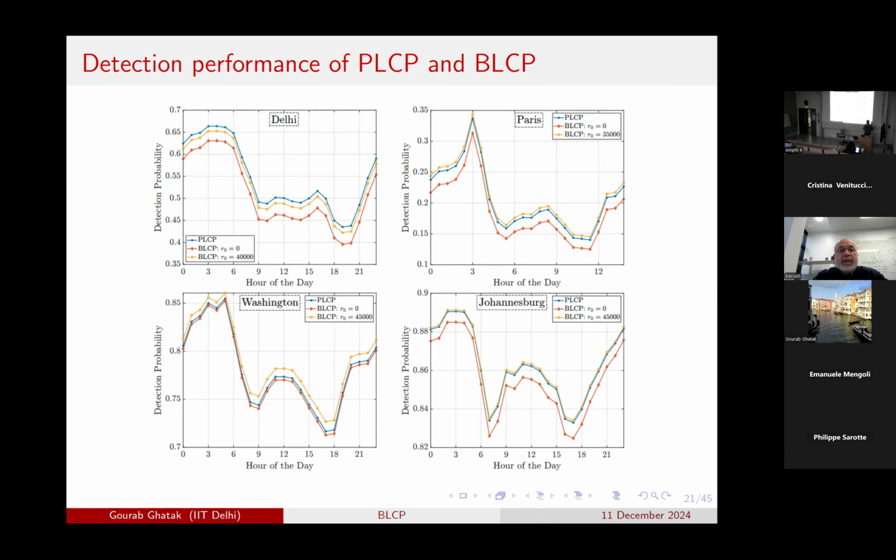Okay, so on the basis of this, we plotted the detection probability, which is the probability that the SINR of the radar signal is greater than a certain threshold, for different cities. Here we ignore the penetration losses due to buildings, but they can be included as well, and they will be included in all different cities as well. We have a stark difference between cities. So here we have 25% or 0.25 detection probability, whereas in cities which have more streets like that one, just because you have fewer vehicles, you have less amount of interference and less detection.